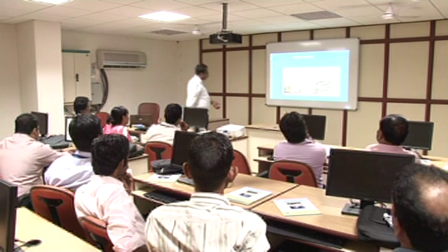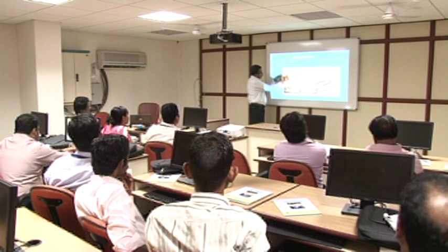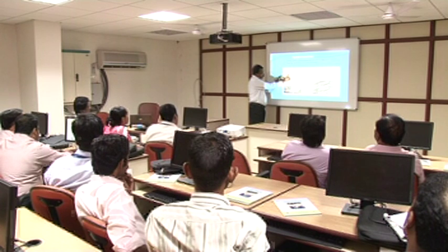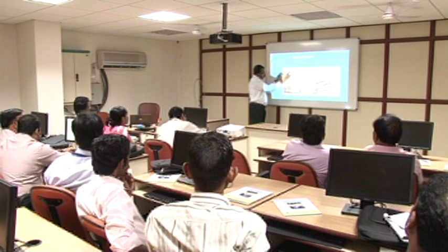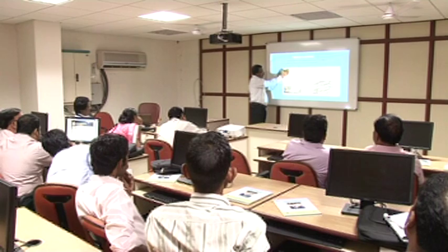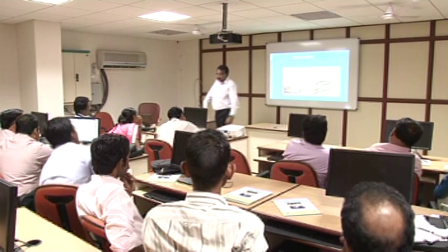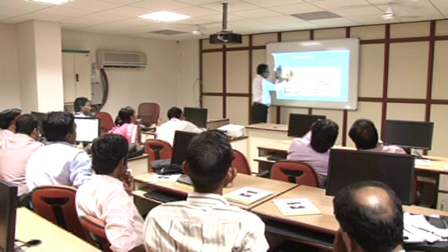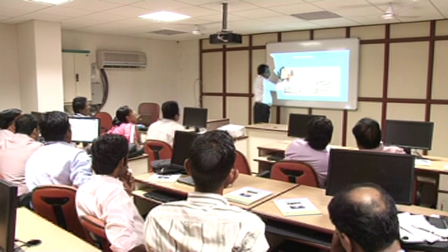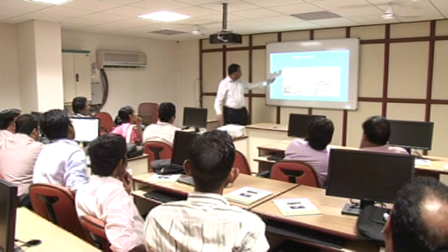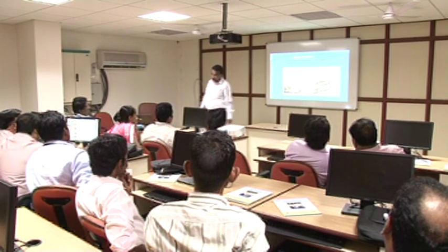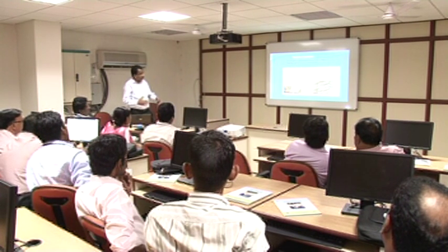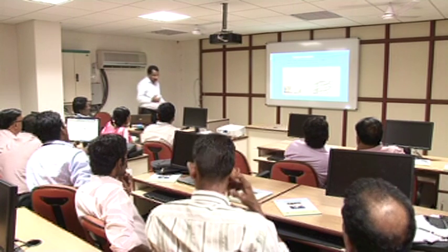Similarly, this one also. This is band 1. This is 500 to 600 nanometer or 0.5 to 0.6 micrometer. So radiation which is coming from the ground objects will be sensed according to that range. So this is split into 3, so that you can say that this is from visible to near infrared, it is 4 bands or 3 bands. Then you can say that the spectral resolution is 3. So that spectral range has been split into 3, so that we can identify.